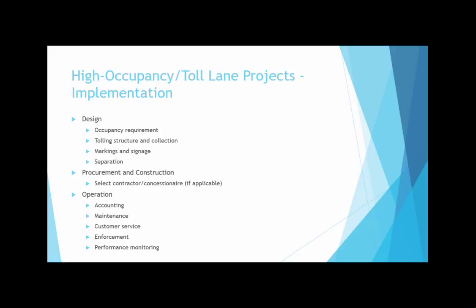How is the toll structured and how will the toll be collected? The tolling structure can be a set structure, so a set schedule of fees that may or may not change during the day, or you can use dynamic tolling, so that's a real-time update in tolling. The San Diego facilities, I believe, update their tolls every 6 minutes to reflect changing traffic conditions. Markings and signage is also an issue because the people in the area may not be familiar with the concept of an HOT lane.